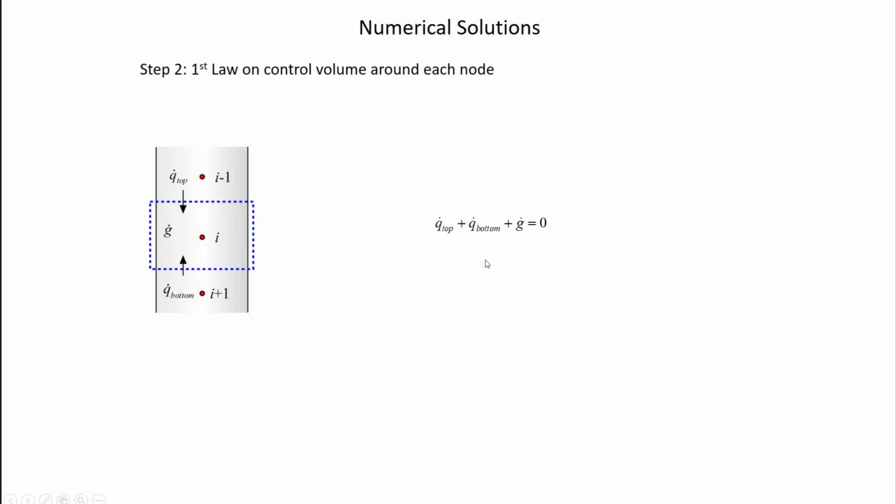And I guess this is a good time to make the point that it doesn't matter which direction I draw these arrows. Right, when I come into this spot right here and I say, I know there's energy crossing this boundary, I actually have no idea which direction it's going. I can draw this arrow as being in or being out, and it shouldn't affect the correctness of your final answer. Same thing for this guy here. But what's very important is that once I decided to draw my arrow going in, well, now I am stuck with that, right? I'm kind of married to that assumption now for the rest of the problem.